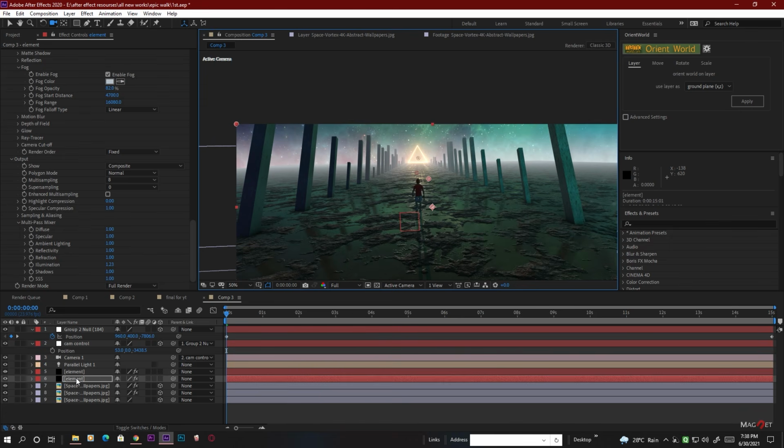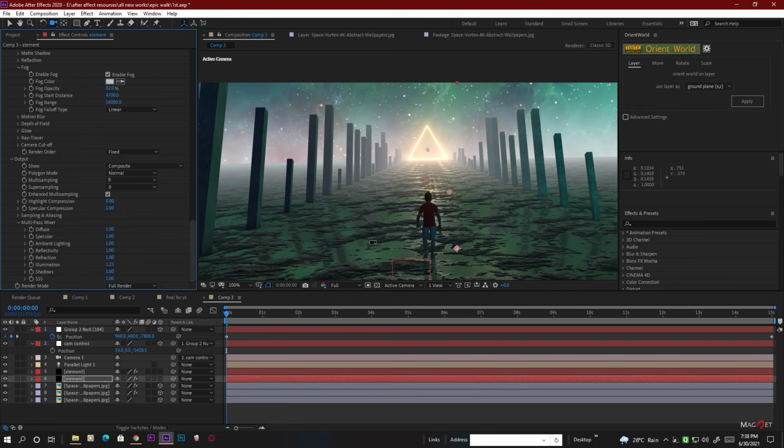And then we do one thing: go to the element layer and there is an option called enhance multi-sampling. You can turn it on, but I recommend that once you have finished all your setup, you turn this on, but before you turn it on, save your project first. And then we turn this on and you can see some fixing in the edges.